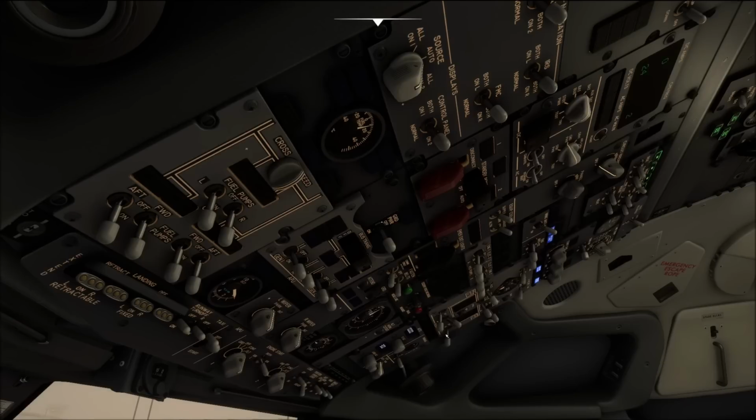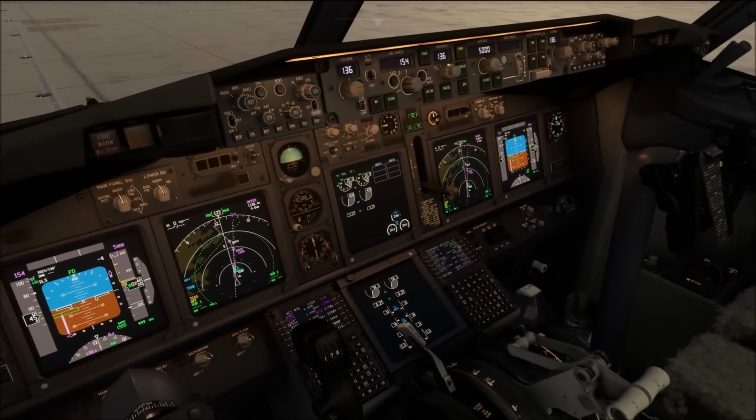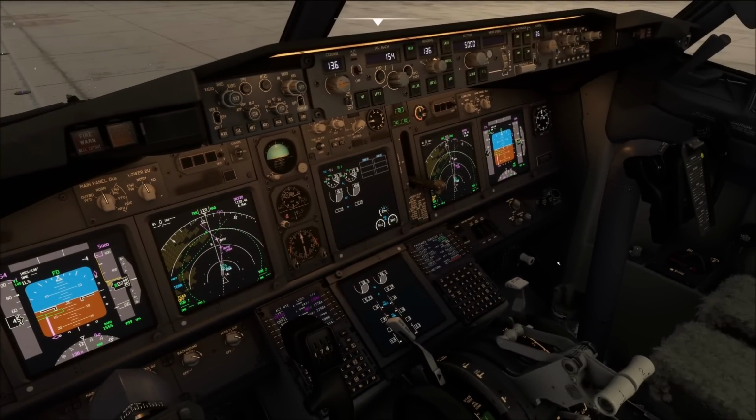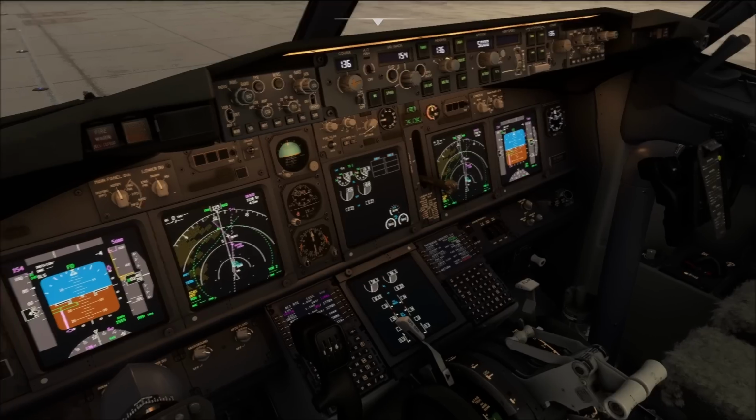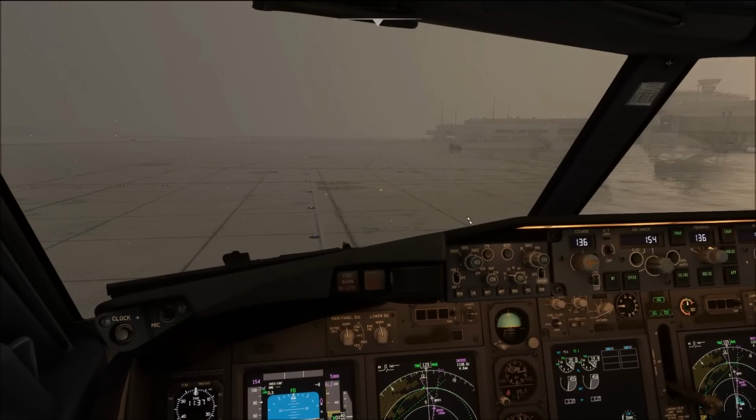Isolation of auto and APU bleed off. But be aware that at least 1 minute should have passed before you switch on the packs after your anti-icing. Now comes the big question of the flaps. The flaps should only be extended when there is no delay anticipated for takeoff, when there is freezing precipitation.